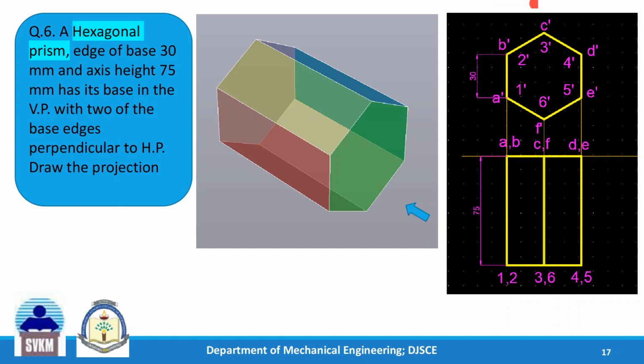in AutoCAD. So these have been drawn in AutoCAD. This hexagon is seen in the front view now with two of the edges, this one and this one, perpendicular to XY. And this is the top view. We are going to see it from this direction and get these two rectangles. This is the rectangle for this, and for this this is that rectangle. Fine.